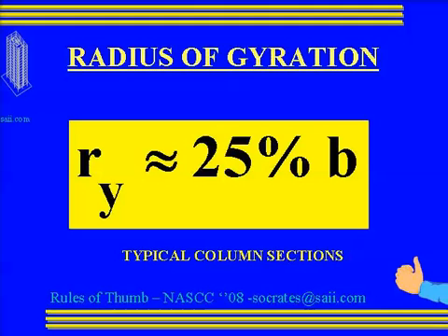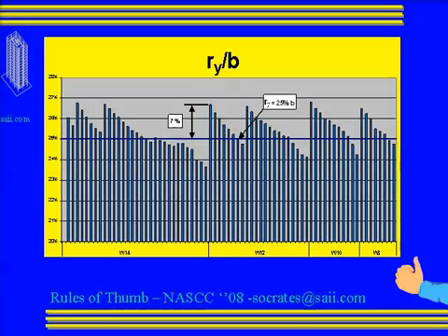Okay, so far I've been dealing with depth and weight that you always know, right? So now all of a sudden, we have the width of the flange. If you're designing long enough, you probably have a fair idea about where you are. But if you don't, this trusty card that you're going to get at the end of this, and I promise you, I think I have enough for everybody today, actually has some column sections and the width of the flanges listed on there. And again, here is a relationship, the comparison.